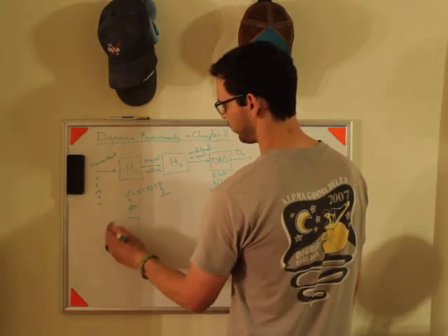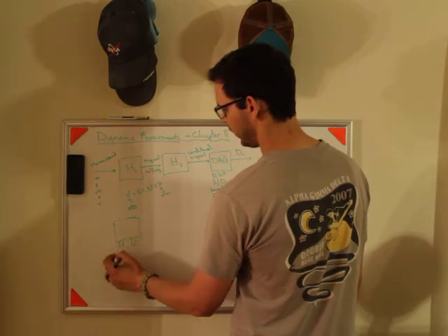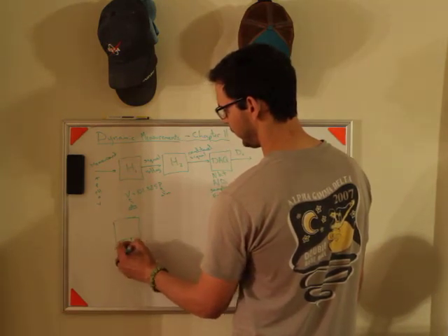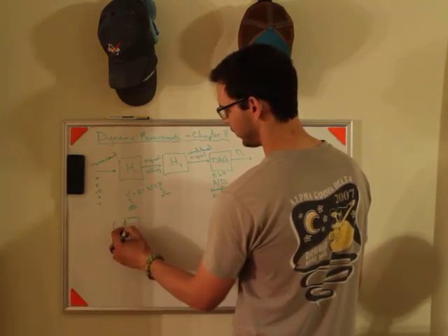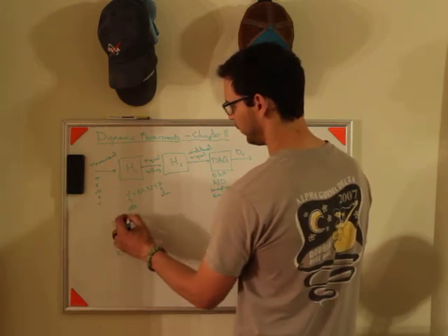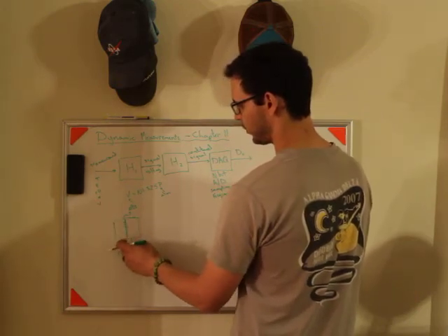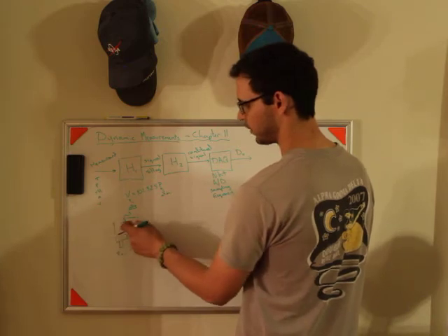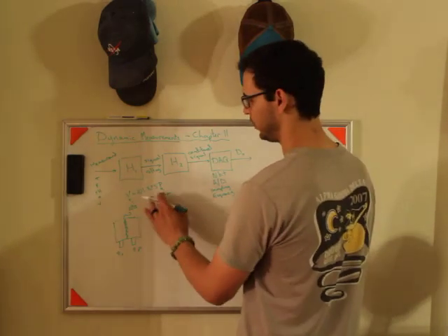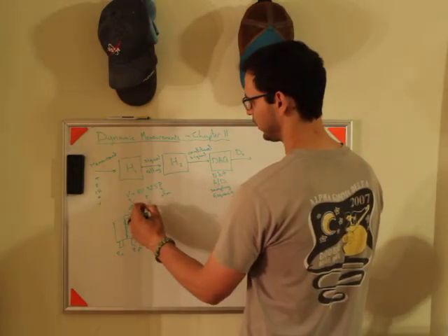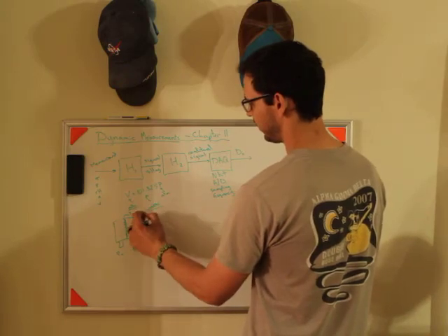And so if you have a pressure transducer here with an input, let me put the input ports down here. If I have a P naught and a P infinity, and I have a strain gauge here, right? And this is going to output a voltage. If the pressure in the stagnation port increases and stretches the strain gauge, it's going to output a voltage, and it's going to be proportional to this. And this is linear, right?